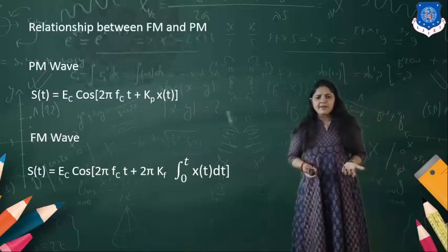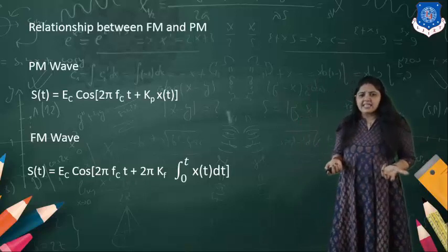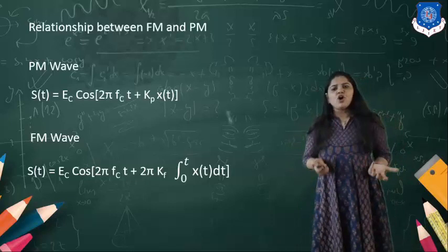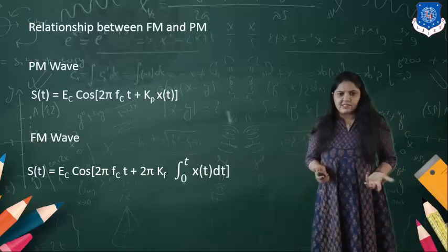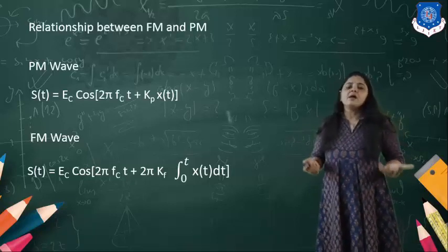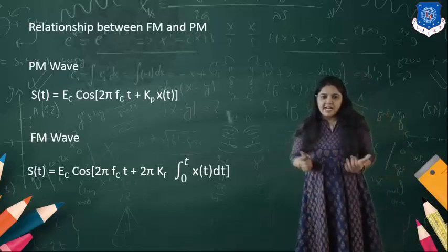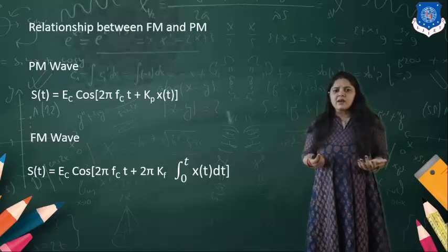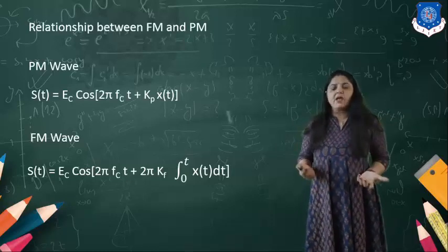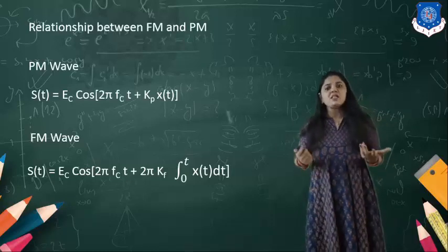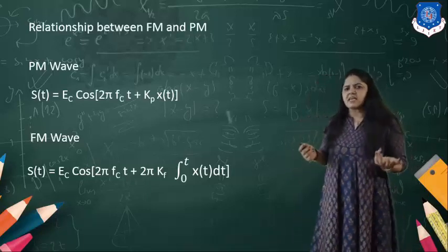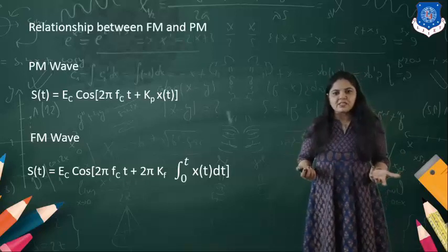As we know, in case of the direct FM method, the frequency was not stable. That is why we may not use the direct FM method in case of broadcasting. To get a stable frequency, we may use the crystal oscillator for generating the constant as well as the stable frequency.